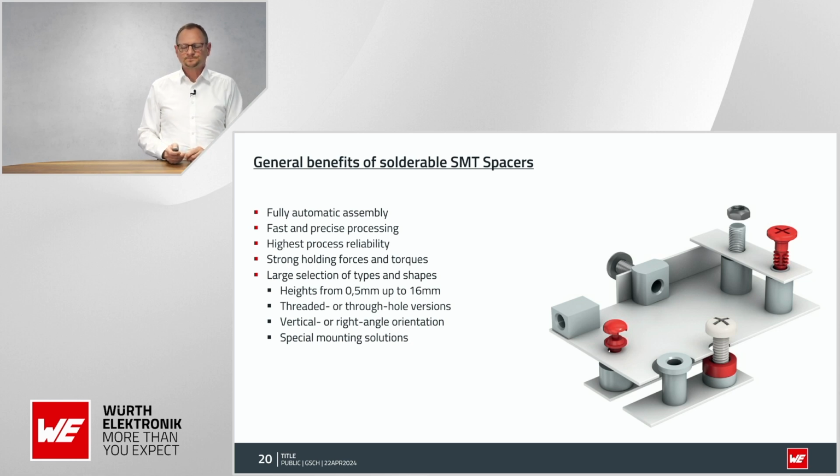The benefit, or the main argument, is that you don't need a second reflow process. You just assemble it from the top and you solder it also from the top, but it gives you a distance to the bottom side. Yeah. So which one else do we have?